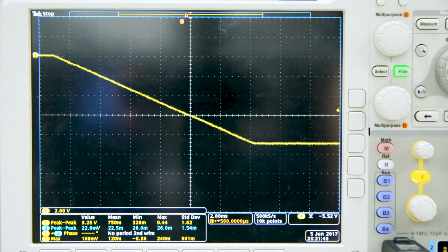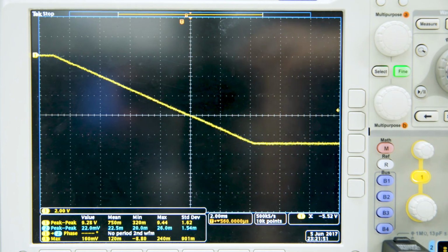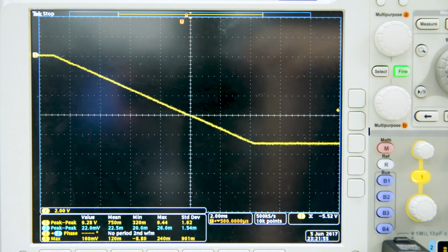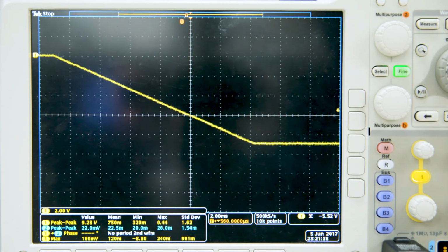So you can intuitively see that the larger the input voltage is, the sooner the integrator output will reach a certain level. So if you can measure the time it takes for the output to reach that level, you can now relate between the analog input signal and a digital measurement of time, and thus you have converted an analog signal to a digital one. Various other methods also exist that use this same circuit as part of their architecture. This is just one of the ways that it can be used as an ADC.